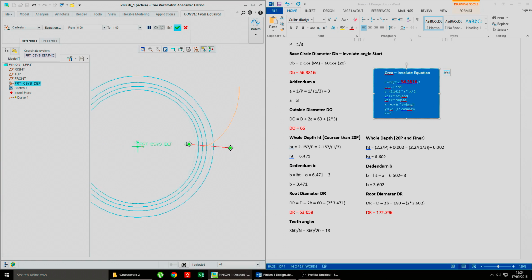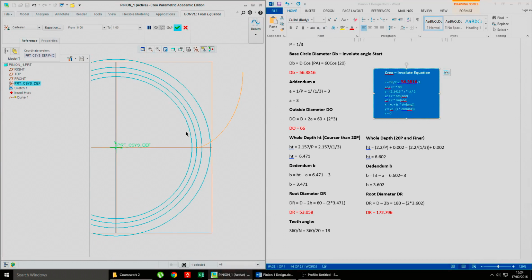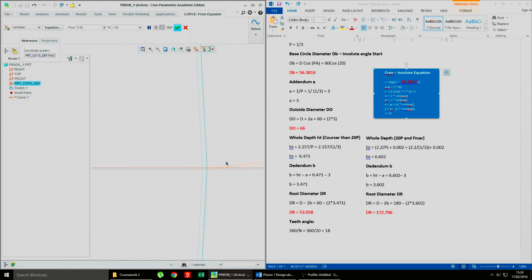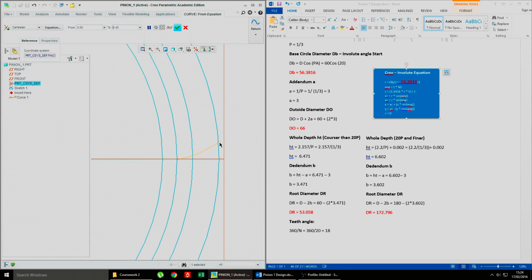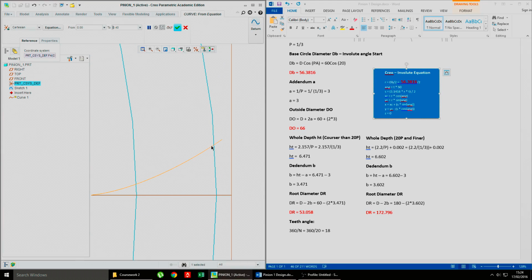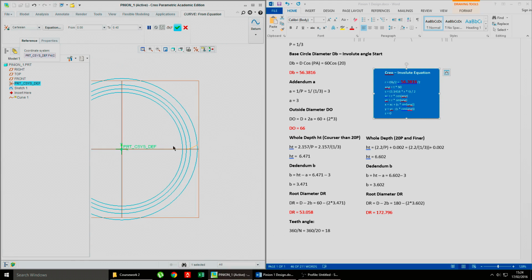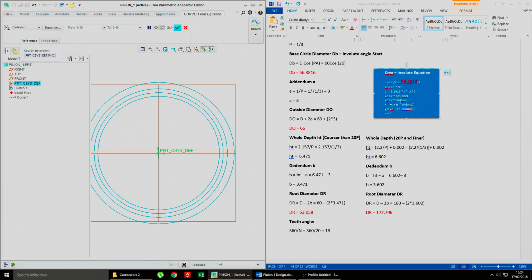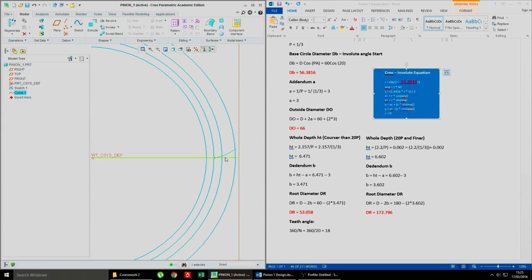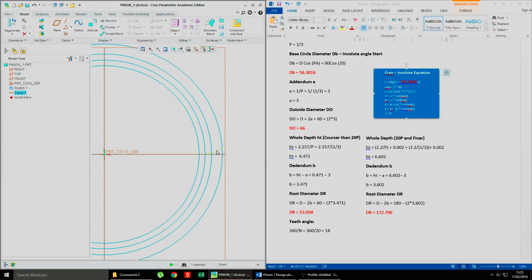As soon as you press OK, you'll see something here. There is an equation here. There is a curve, a really weird curve I might add. With this curve, from 0 to 1, change that to, I don't know, 0.3. Let's see what happens. No, that's too small. Change it to 4. Yeah. So you basically want the outside edge of this curve to come out of the last circle, the largest circle, and that will make life a little bit easier for you. Press OK.